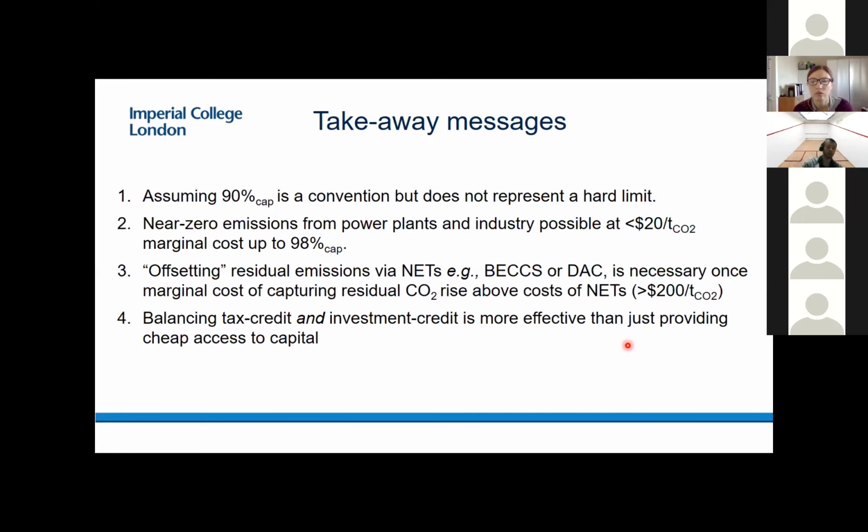Oh, right. So the absorber is modeled at 40 degrees Celsius, and the CO2 flue gas that comes in is preset. So I've got a direct contact cooler, so all the flue gas will be cooled down. And depending on your flue gas composition, that temperature changes. So I took some reference cases from NGCC power plants to coal-fired power plants to hydrogen plants and so on. I think it depends on what you can reject heat at from the system, you know?